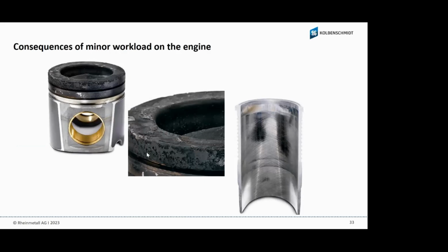And this is what I said before, we also need a rough area on the cylinder bore. There the oil can be clamped on it, and when it's missing, the oil drops down. And this is the quick effect. When we have carbon built up on the top, they polish the cylinder bore.